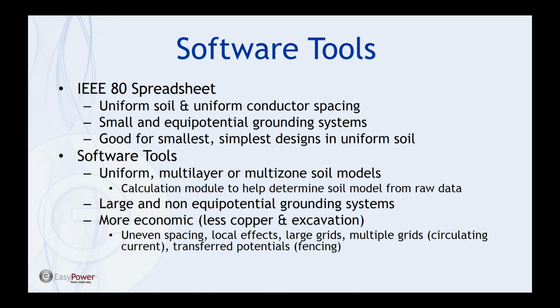Transferred potentials being those where maybe you have a fence running adjacent to your site and you want to know whether or not you want to ground that in a certain way or connect it to your site. And so you can model that, and you'll see the potentials developed around the fence and on the fence as a result of that, and determine if that's also safe for step and touch during your fault condition.